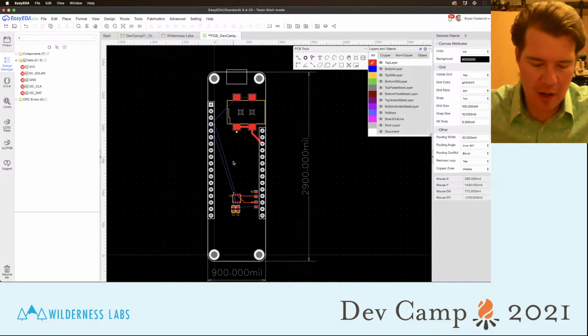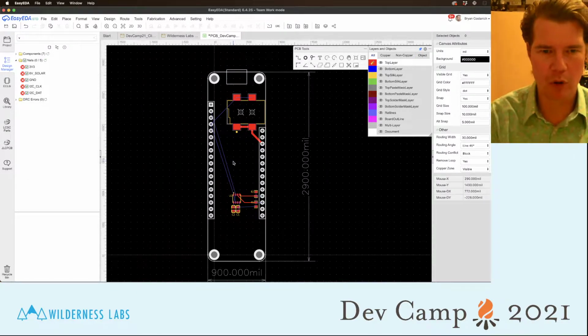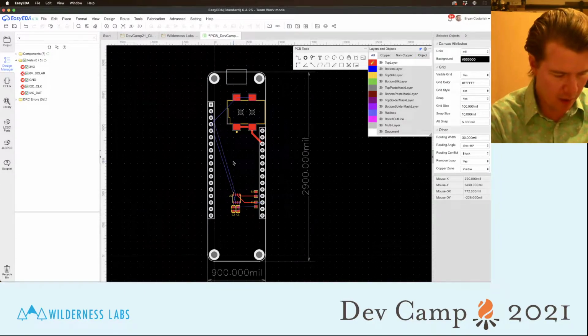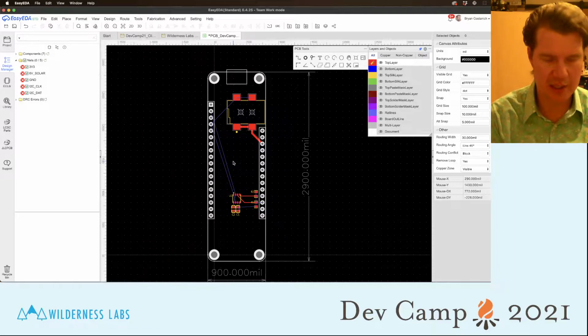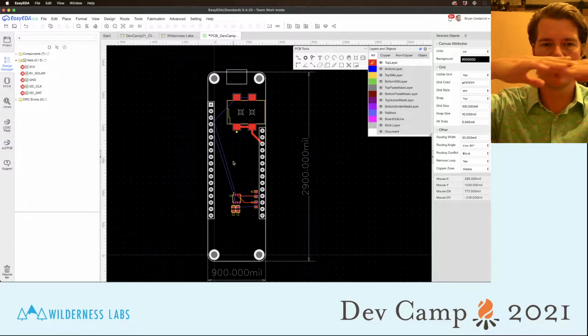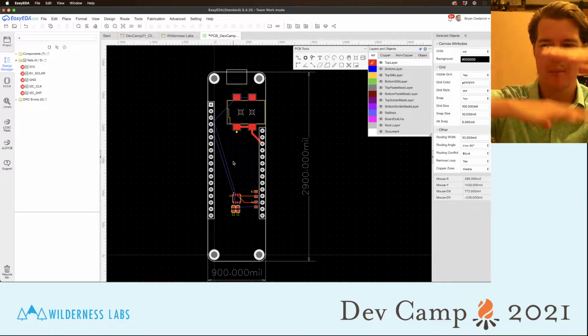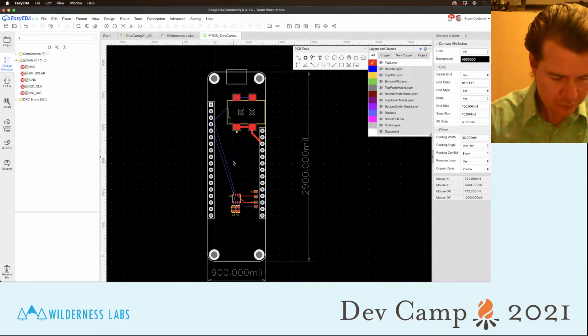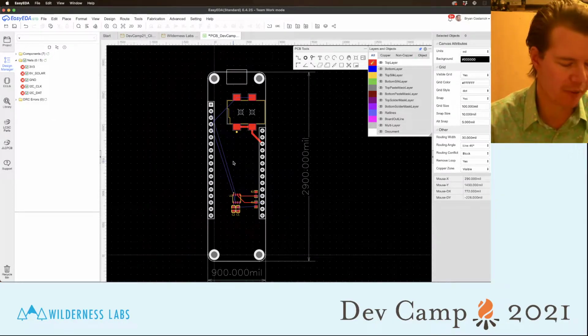And that brings up another thing that we should talk about, which is multi-layer boards. Most of the boards that you spin are going to be simple 2-layer boards. That means they've got a fiberglass core, and you've got copper on top and copper on bottom. And the copper is what constitutes a layer. And that's where your signals and your power and stuff is routed.